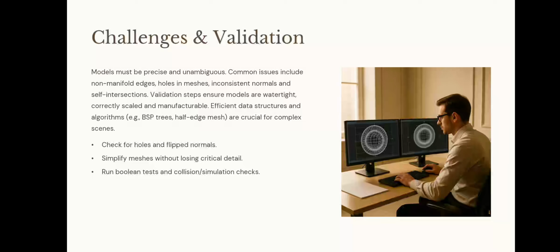Challenges and validation. Models must be precise and unambiguous. Common issues include non-manifold edges, holes in meshes, inconsistent normals, and self-intersections. Validation steps ensure models are watertight, correctly scaled, and manufacturable.